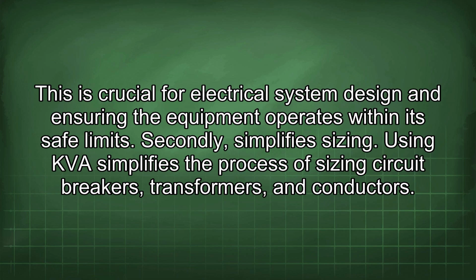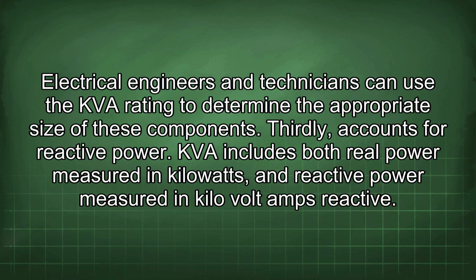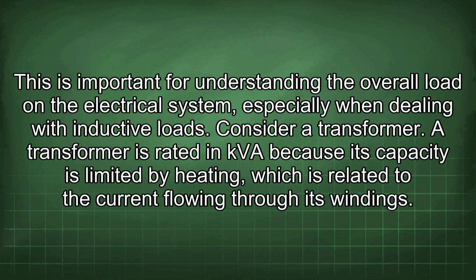Secondly, simplified sizing. Using kVA simplifies the process of sizing circuit breakers, transformers, and conductors. Electrical engineers and technicians can use the kVA rating to determine the appropriate size of these components. Thirdly, it accounts for reactive power. kVA includes both real power measured in kilowatts and reactive power measured in kilovolt amps reactive. This is important for understanding the overall load on the electrical system, especially when dealing with inductive loads.